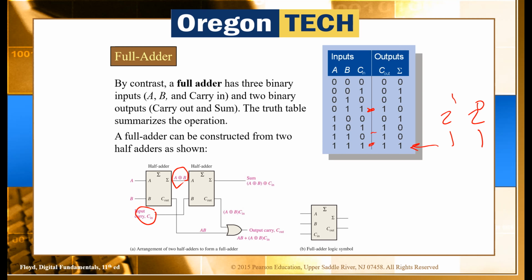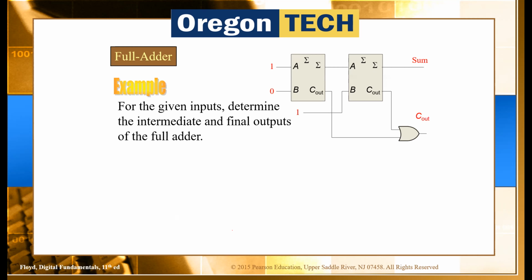And what will be the carry out? The carry out, as we have seen before, takes the carry out of the first stage and the carry out of the second stage, ORed together. I am ORing the two carries. Now let's see this example.